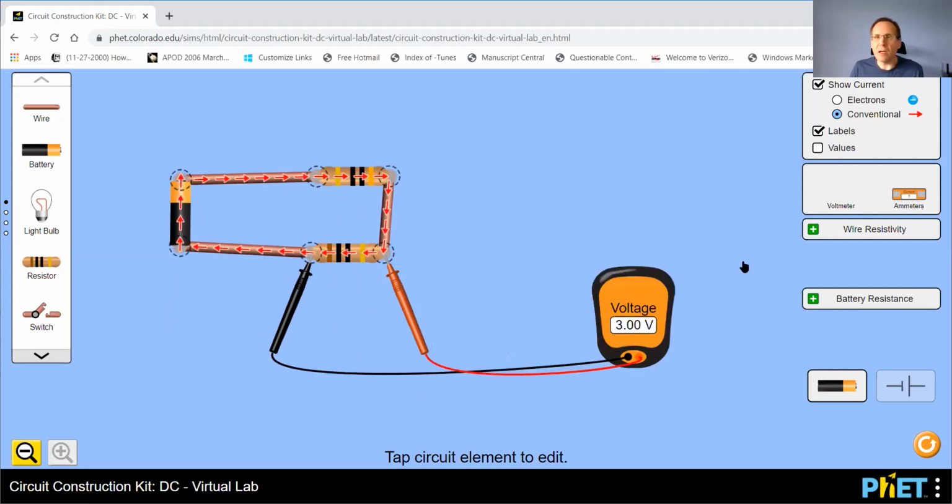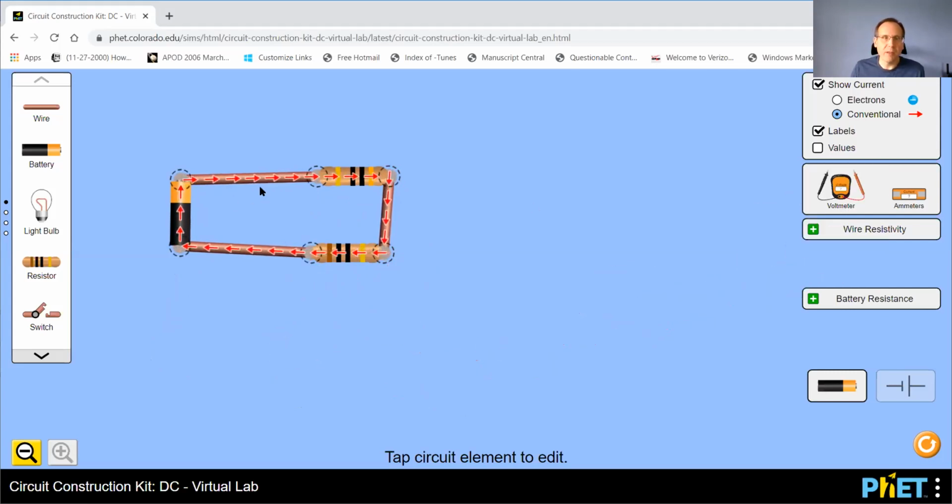And then to measure the currents, remember, you want to measure the current here at this location, at this location, and this location. So you have to separate this, right? Cut it, maybe shrink this a little bit, and then grab your amp meter, stick it in the circuit, and then that would be I1, right? That would be at that first location, I1. Then you do the same thing here, I2, and then I3. Okay, so that'll give you all of the values that you need.